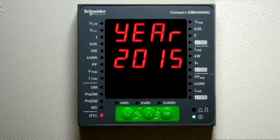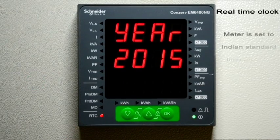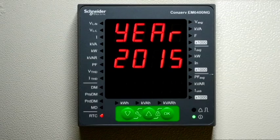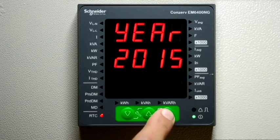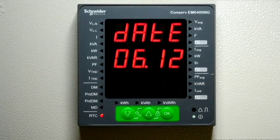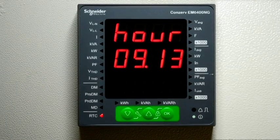Next set of settings are related to the real-time clock. The meter clock is set to Indian Standard Time before it is dispatched from the factory. However, the meter also provides an option to set the date and time for different regional timings. This is year. This is date in MMDD format, and this is time in hour and minute format.